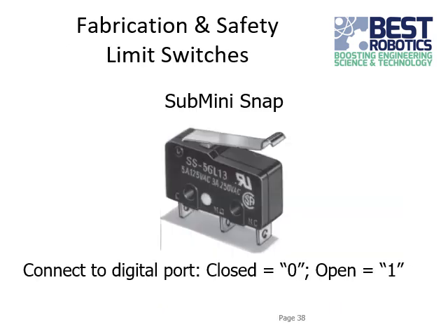Here's another nifty little component called a limit switch. These are just little switches that you can have your code read as a 1 or 0, depending on whether it's pushed or not pushed. This can be a way to have software controlled limits on how far an arm can rotate, or to tell if your robot has bumped into something that you might not be able to see from the spotter's box or the driver's box.